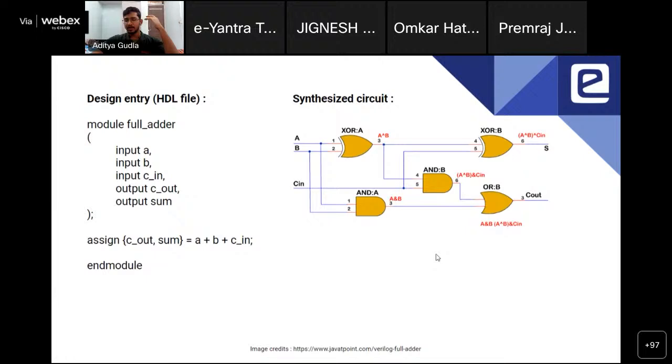In tri, the output can basically have three particular values. It can either be 0, it can be 1, or it can be in high impedance state. So that is a tri node. High and low are digital logic. High impedance means it is not connected to anything. It offers very high impedance, so it is basically not connected to anything. That is the meaning of high impedance state.